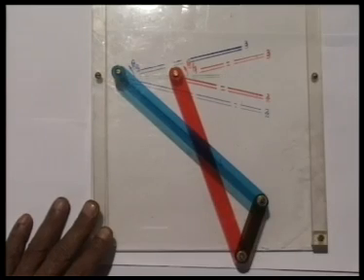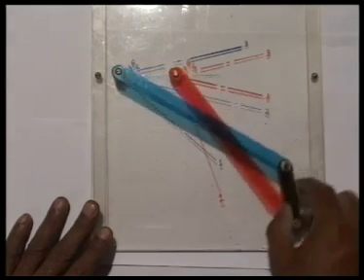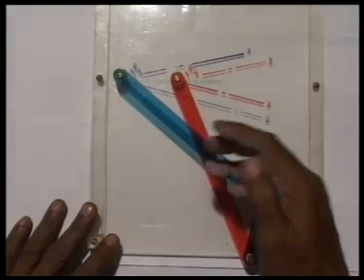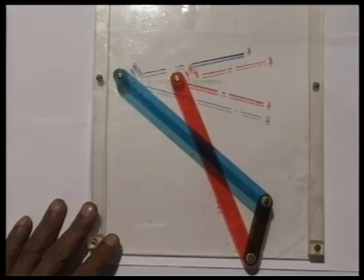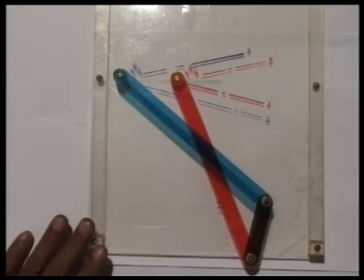But as a mechanism, this will be useless because the switchover cannot take place as soon as it becomes a non-transitory Grashof linkage, and various configurations may be taken up by the different modes of assembly. That has to be checked after we get the design parameters, whether by graphical method or by analytical method.